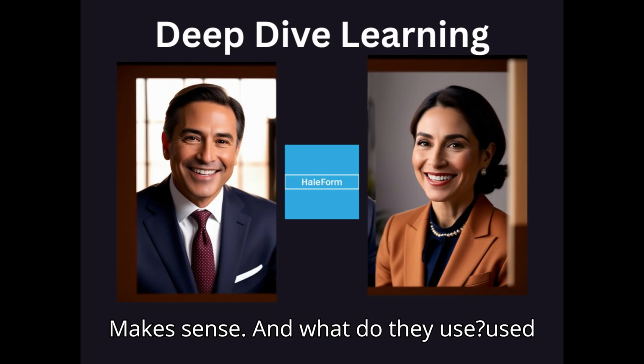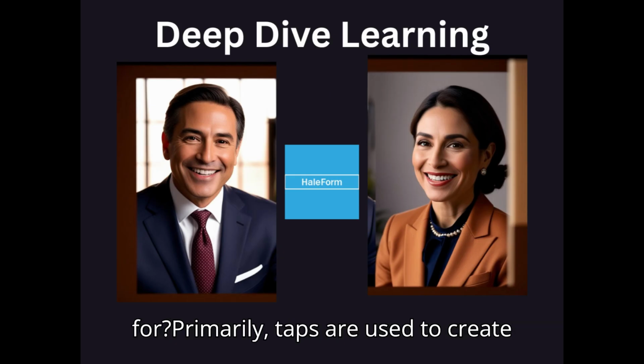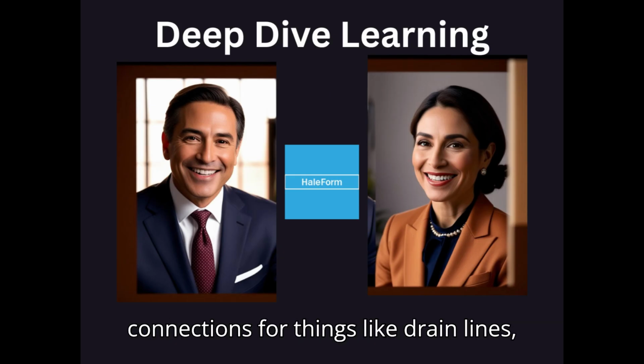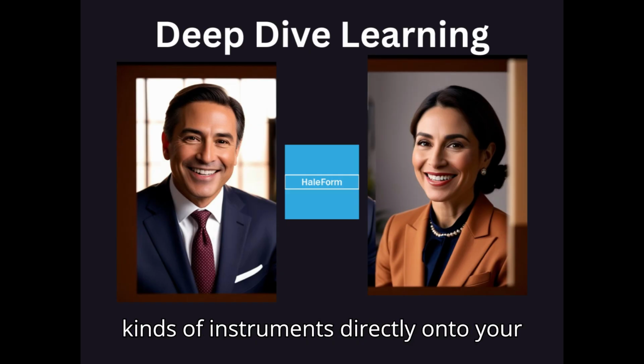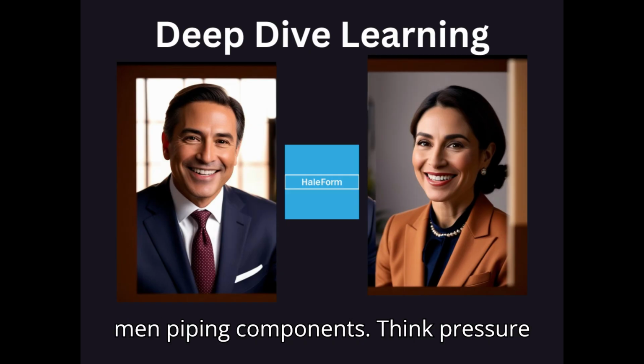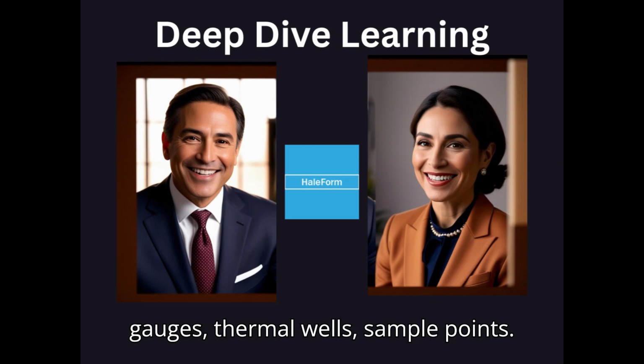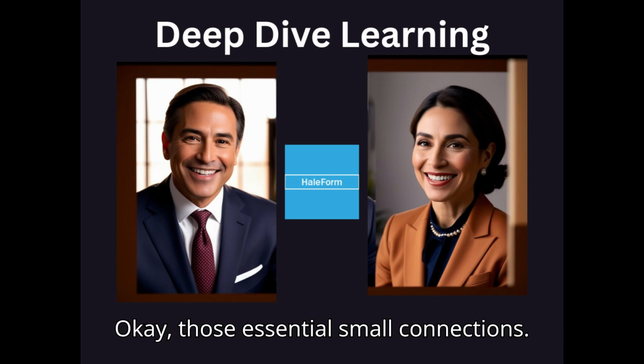Makes sense. And what are they used for? Primarily, taps are used to create connections for things like drain lines, vent lines, or for attaching various kinds of instruments directly onto your main piping components. Think pressure gauges, thermowells, sample points. Okay, those essential small connections.